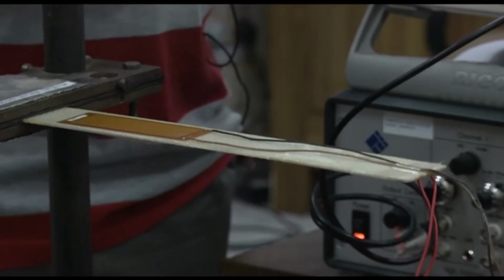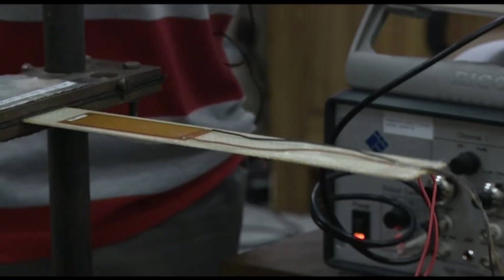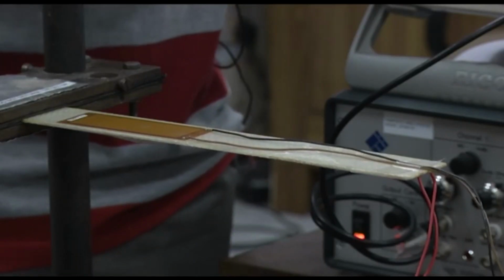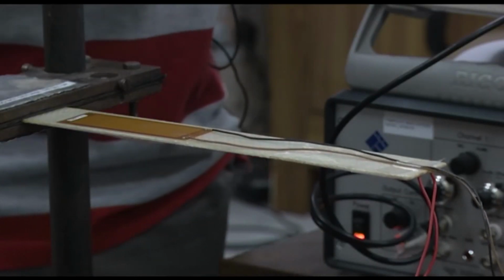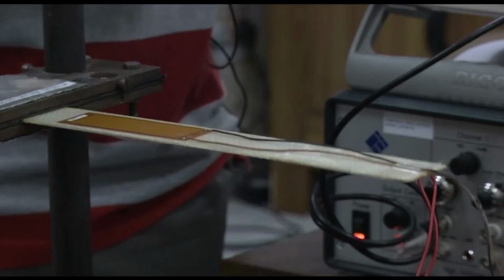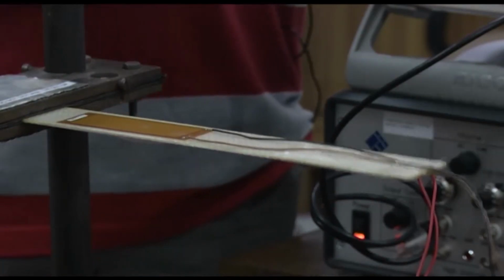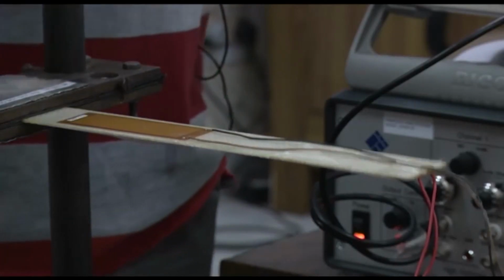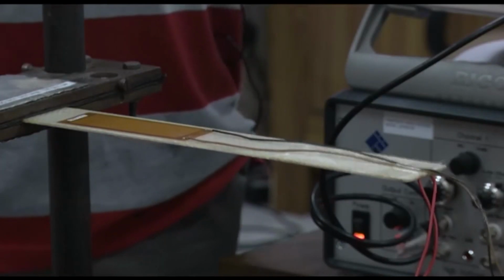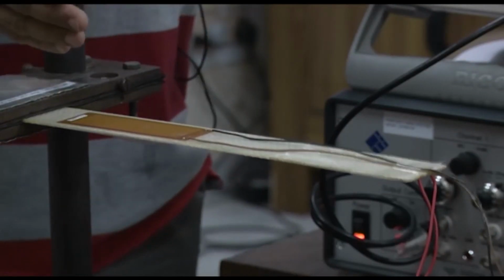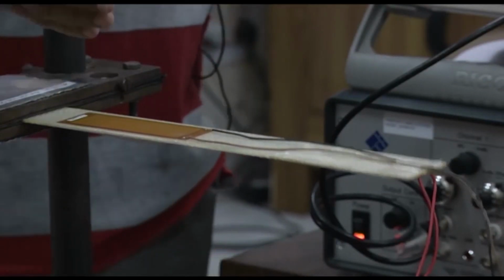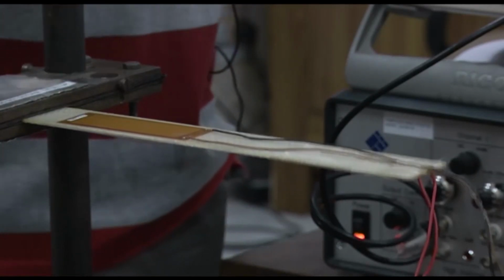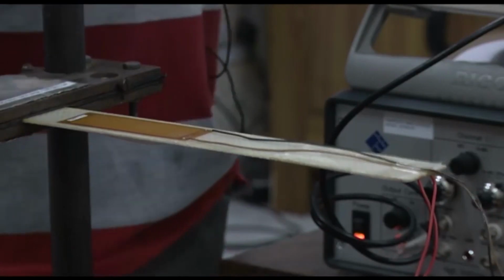Maybe we can try up to 11 Hz, but you can see that as we have approached 11 Hz, now the amplitude is coming down. If I go further, 12 Hz, you can see the amplitude is coming down. Which means if I go back to close to 10 Hz, it is one of the natural frequencies of the system, and at that frequency the MFC is able to excite this flexible beam. So through this we are demonstrating how you can use this macro fiber composite to generate dynamic actuation forces on a flexible beam and to generate vibration as a result of it.